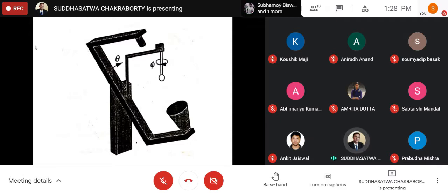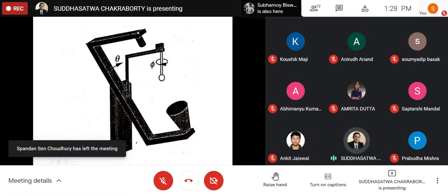But if I fix my source at a particular angle, say 0 degree, and here is my sensor mounted at the bottommost portion of the conical shaped baffle. Why a conical shaped baffle? Why this arrangement? We will come to that point. But right now I can tell you, at the bottommost portion of it we have the sensor mounted, and we are allowing the sensor to be rotated about this axis. So if I rotate 360 degrees, what am I going to get?